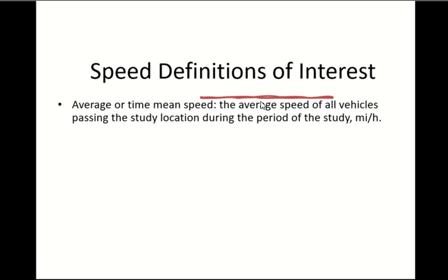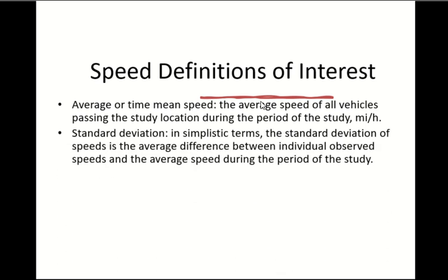Now what did we call this? Spot speed, right? A speed over a spot. So now tell me, time mean speed or space mean speed? Time. There is no spacing. So when you take spot speed data and take its mean, it is called time mean speed. Mean of spot speed is time mean speed. Clear? And we know how to take it and what it means.